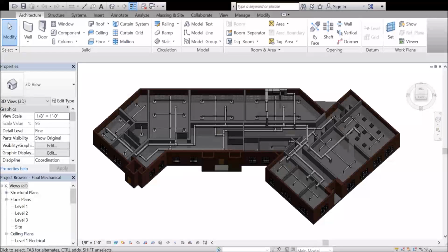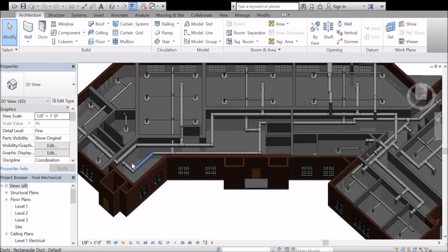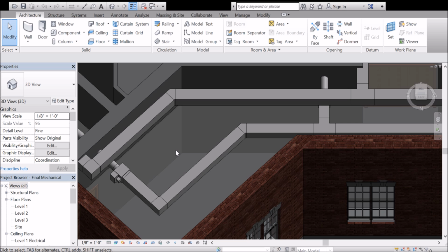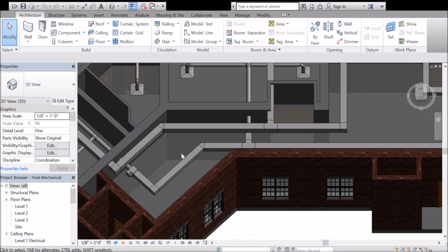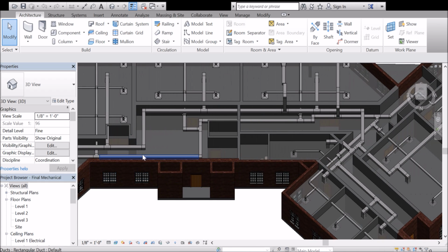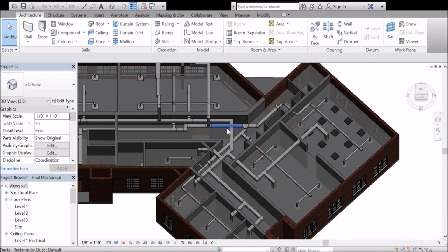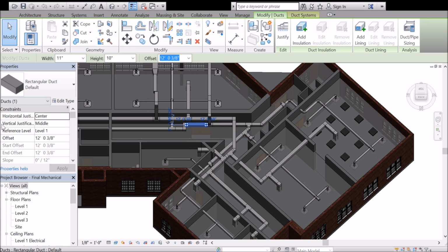And we're going to do that by using square ducts. So if we zoom in here, this is the exact same process we just used for drawing our round ducts, except they're going to be square. So you're just going to draw square ducts connecting everything together. So mine runs here, I grab that VAV box, I already grabbed those two, runs here, grabs that one, and then on this end I grab this one here, and this one here. And make sure you go in, and once again you're going to have to change your routing preferences. So under Edit Type, my routing preferences are these. You can either pause the video here or just look at the assignment page and go ahead and load everything in so that your preferences look identical to mine.